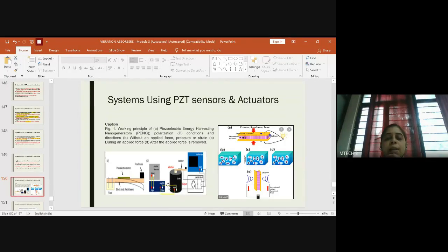So if you provide an input in the form of an electrical signal, then only the shaker can shake and you can get the required results in the form of vibration of the cantilever beam, and the required displacement will help you to evaluate what is the strain rate which has been induced. So based on the data of the analog controller, you can get the required variation in the strain rate. And hence you need an amplifier unit as shown in the diagram over here.